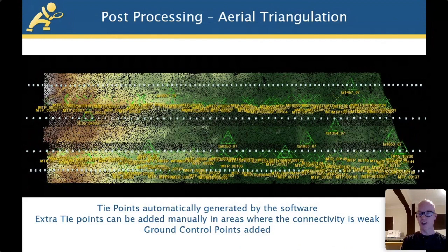And what the software does, it puts all those images together in your flight, several thousand. Then it finds tie points, so common points of the same pixel brightness value. And it uses those to make micro adjustments to the position of every image relative to every other image. If you think back to our high overlap, there are going to be hundreds of thousands of tie points.